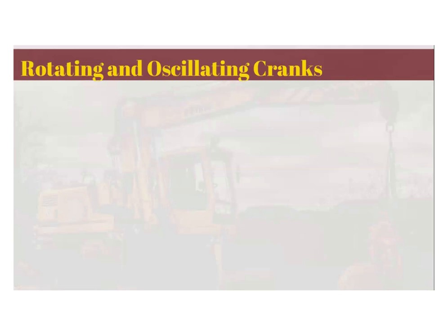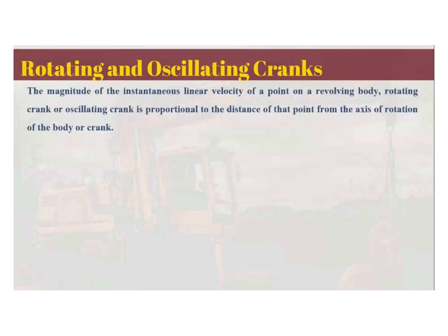Another consideration is for you to familiarize yourself with rotating and oscillating cranks. It is said that the magnitude of the instantaneous linear velocity of a point on a revolving body, a rotating body, or an oscillating crank is proportional to the distance of that point from the axis of rotation of the body or crank.